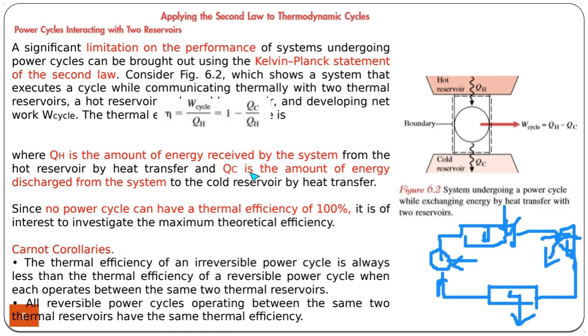And as a matter of fact, it's most of the time much less than 1. For instance, for a system such as this one, the efficiency is around 30%. For an internal combustion engine, it could be as high as 40%. For a gas turbine, it could be as high as 50%, and so forth. For a fuel cell, for instance, the efficiency can be as high as 70%, but it never gets closer to 1 because there is a necessity for some heat rejection. Otherwise, the cycle cannot be completed.